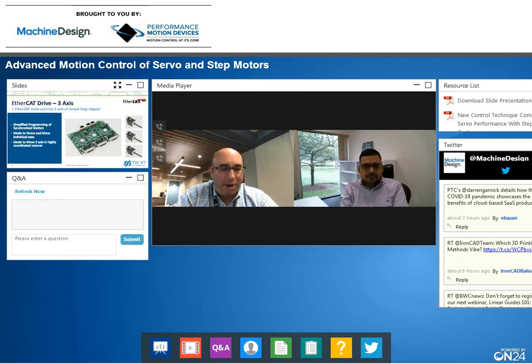And then from that point on, you load it in when you fire up, you know where you are, you set your phase angles, and it allows a lot higher precision of these small motors when you can do a factory setup. Whenever the machine turns on, it's not someone trying to do a factory setup or the machine going through gymnastics. It's an absolute single turn encoder. You pop in the phase angle and away you go. You're going to be set as it was calibrated originally.